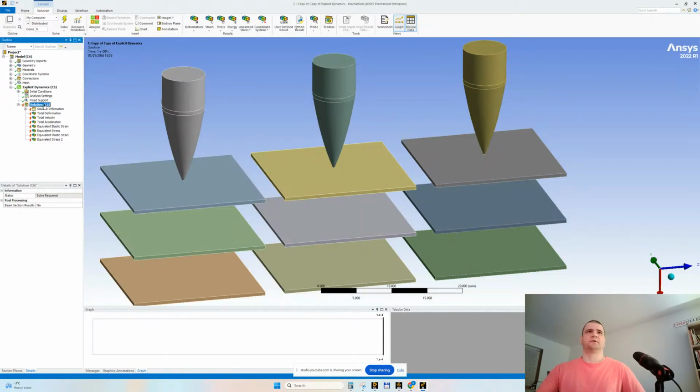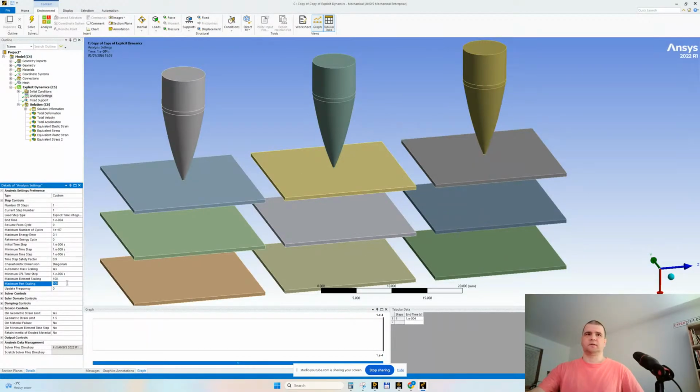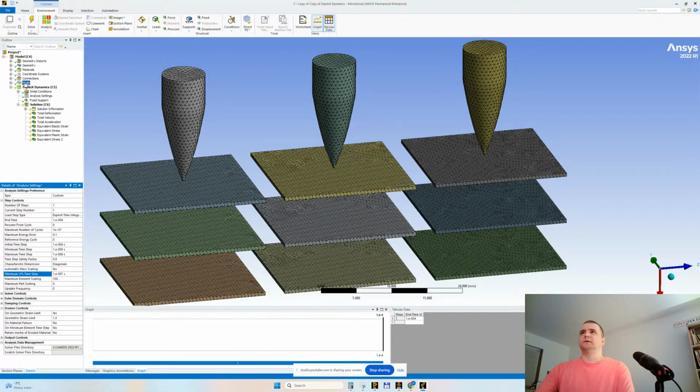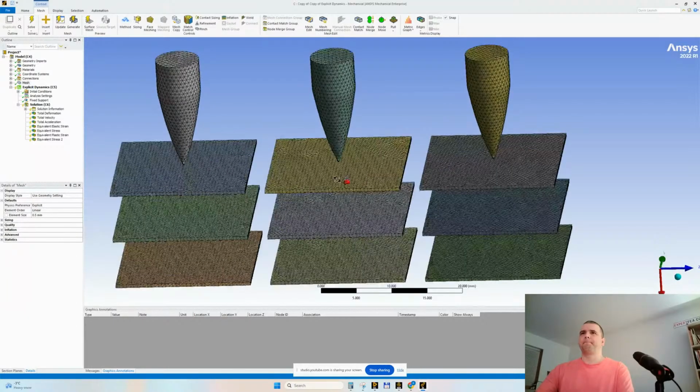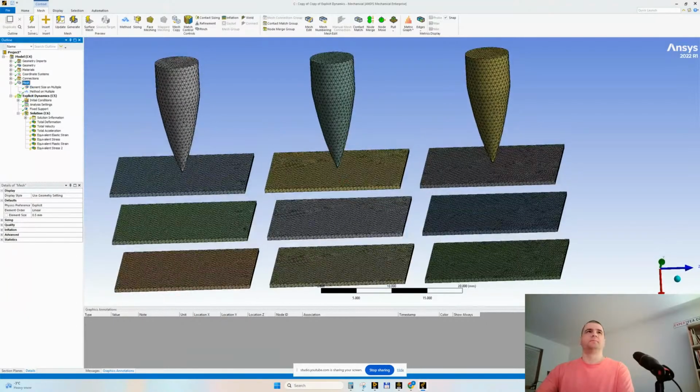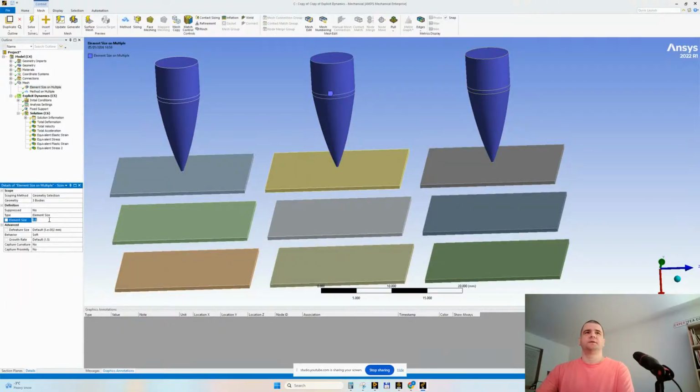The default was 0.05. Let's go back to something more decent. We had 5 in the past, and here we have 1e minus 7. Let's solve that problem with the meshing. There was a problem with the meshing here. How should we solve it? Yeah, change the size. 0.6. Maybe make it 7. Save, solve.